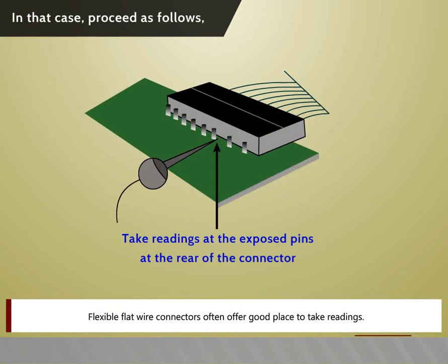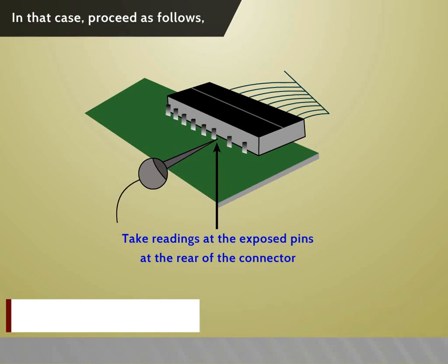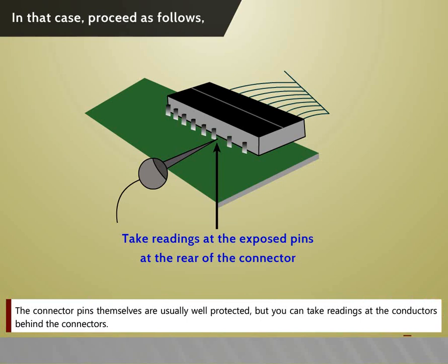Flexible flat wire connectors often offer a good place to take readings. The connector pins themselves are usually well protected, but you can take readings at the conductors behind the connectors.